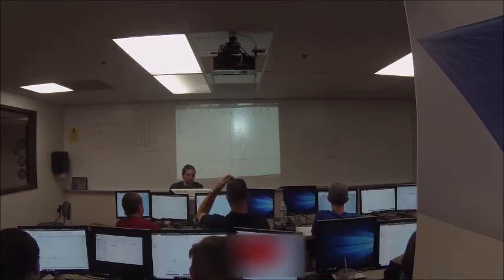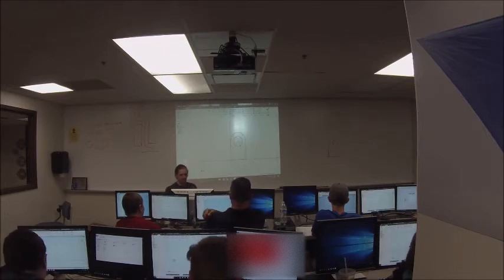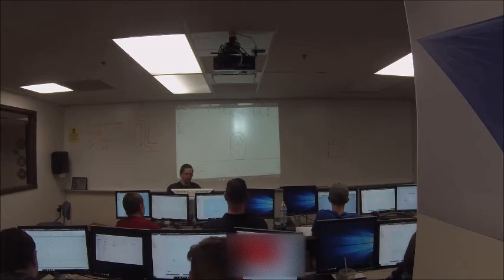Right, and then it automatically places this little dimension that specifies the size. So if I want to make these bigger, like a 1/2 inch, I can double click on the dimension and edit the dimension. Right, now I have bigger fillets. I can make them even bigger if I want to. I can make them 1-inch fillets. Right, round the whole bottom of the part off. Okay, I can always go back and change them.